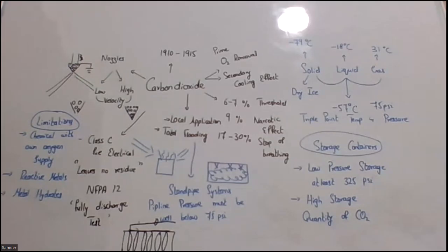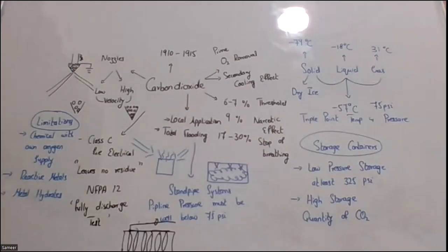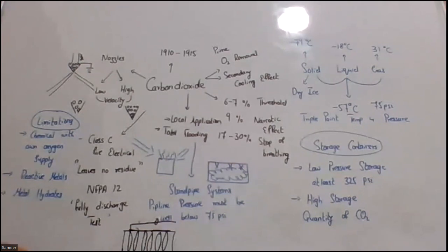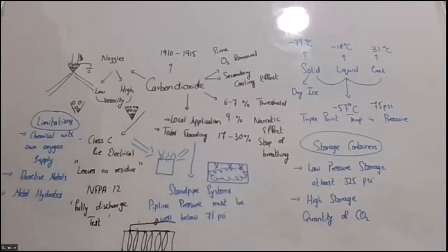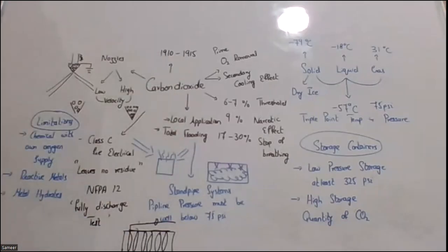How do we check a portable extinguisher of carbon dioxide? And in which form is carbon dioxide stored in a portable extinguisher? Okay, just a second. There are some questions also. Liquid form. It's in a liquid form, right? We have discussed this. It is in the liquid form, right? That is why we check the weight of the carbon dioxide. That is why the weight of the carbon dioxide is always checked in the portable extinguishers.